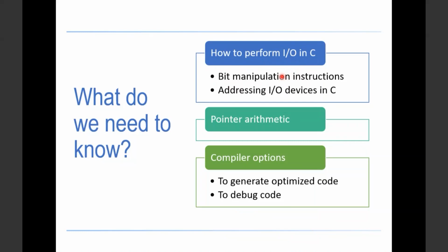You need to do some bit manipulation from your inputs or from your output. For example, you connected your switches to port A pin number 3.